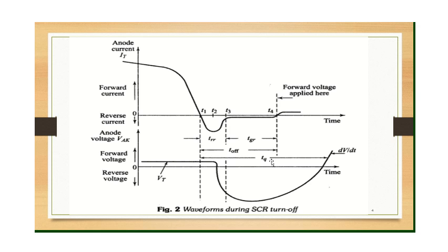All right. So if the thyristor is taking a turn off time of around 50 to 100 microseconds, then we say that it is a slow switching device, or slow switching thyristor. If the thyristor is taking a turn off time between 10 to 50 microseconds, then it is a fast switching thyristor. That means we want the switching to take place faster or slower, right? So based on that, we can categorize the device as slow or fast switching.